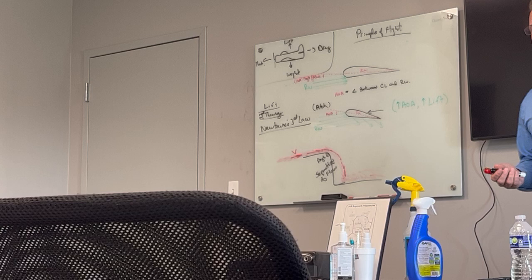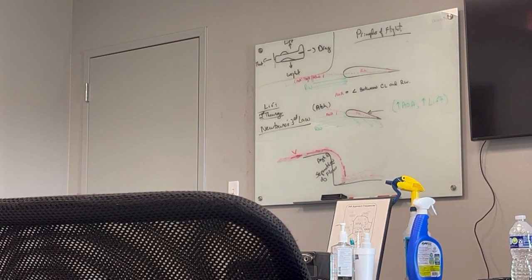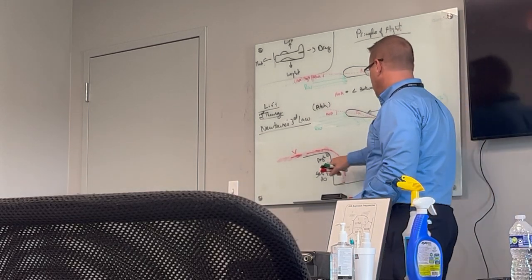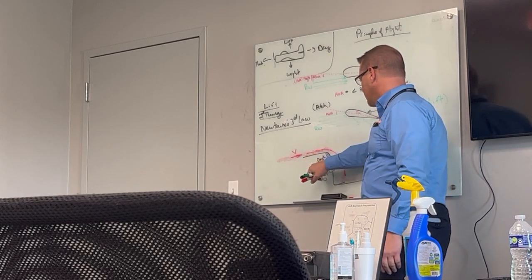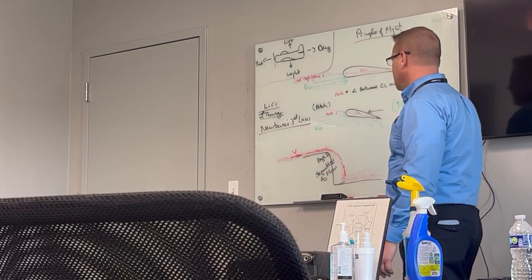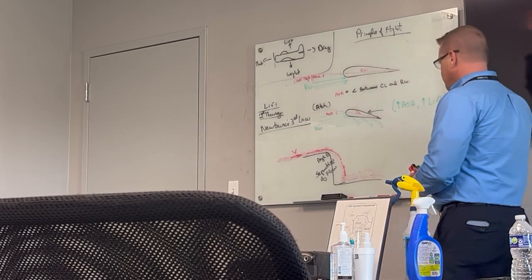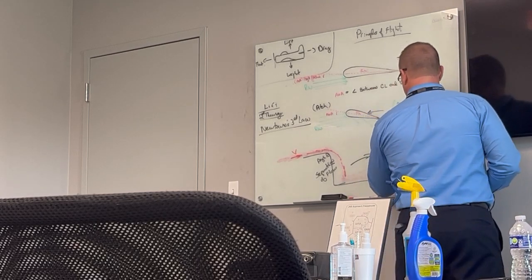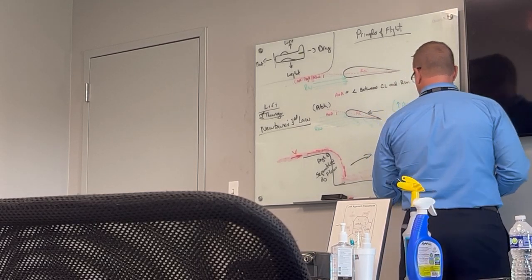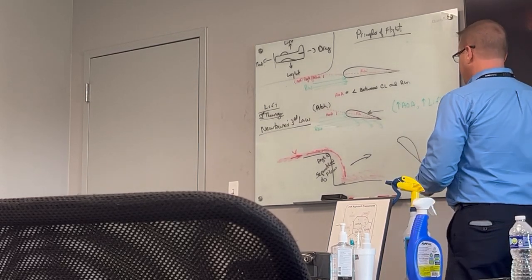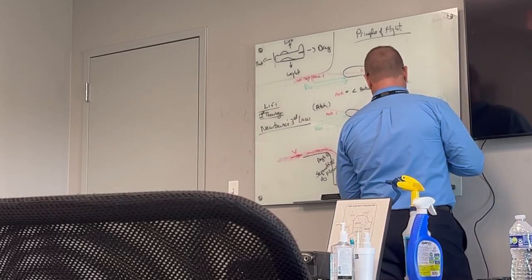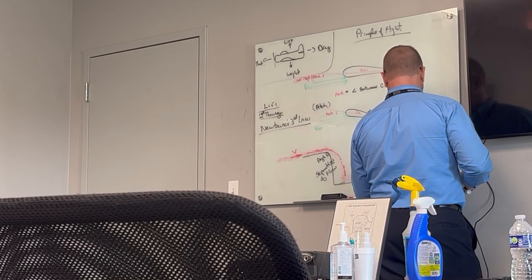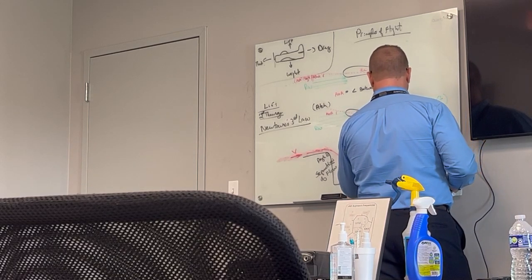Now, if the angle wasn't so steep, say we just had a steep grade, a 40-degree angle or something like that, the water would just keep flowing right down it, right? But at some point, it gets to an angle where, for however fast this water's flowing, it can't do that, and it causes flow separation. Taking that and bringing it into our model here, we have that relative wind, and now we're getting all kinds of crazy deflection off the bottom of this wing, okay?